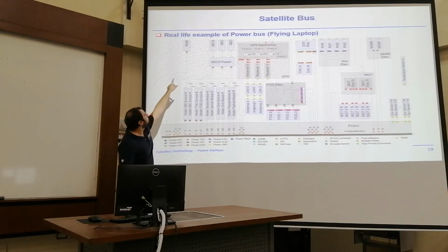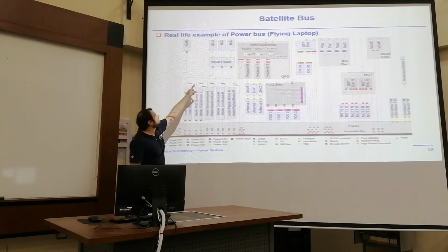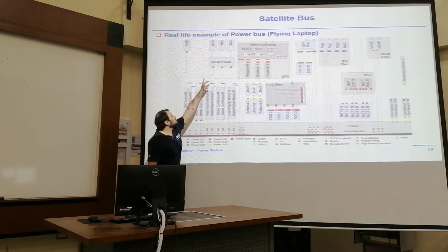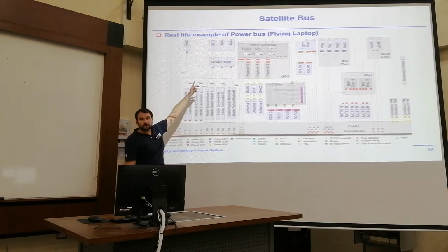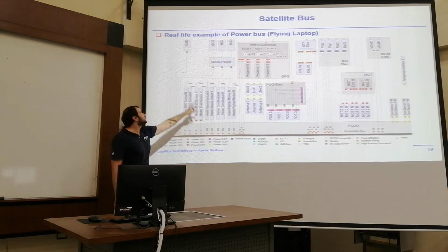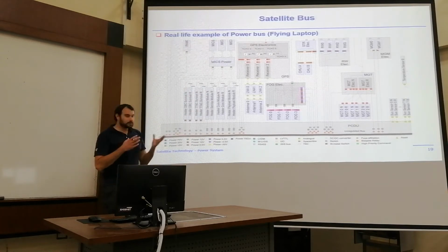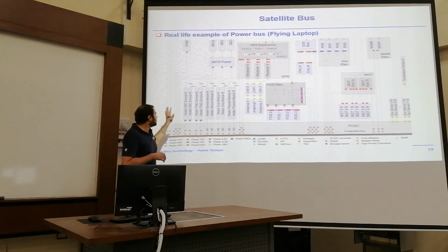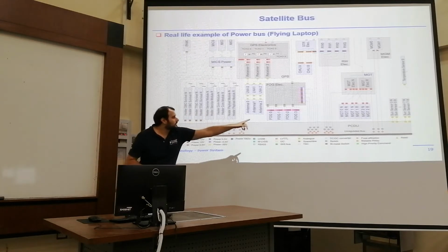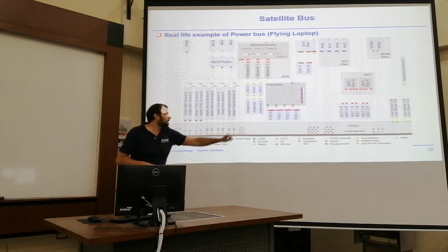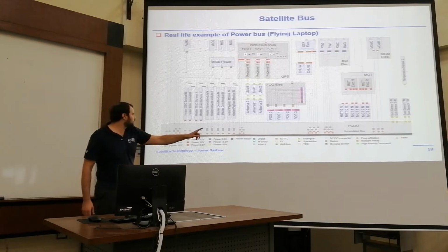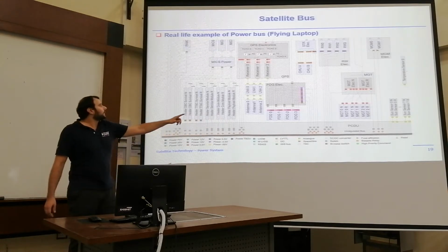However, we see a lot more components, like the multispectral cameras, MIX. They are not connected directly to the unregulated bus. They have a mixed power unit in between. So for most cases, everything but the heaters and the sun sensors on the lower right, they go on minus 30 volts, I guess.